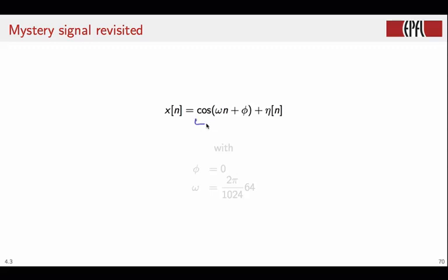There will be a cosine component, and we will have to determine both the frequency and the initial phase of this cosine. And there will be another part that we can probably call a noise component, in the sense that it doesn't have any structure. Since the imaginary part of the Fourier transform doesn't exhibit any particular peak, we can assume that the phase of the cosine is 0.